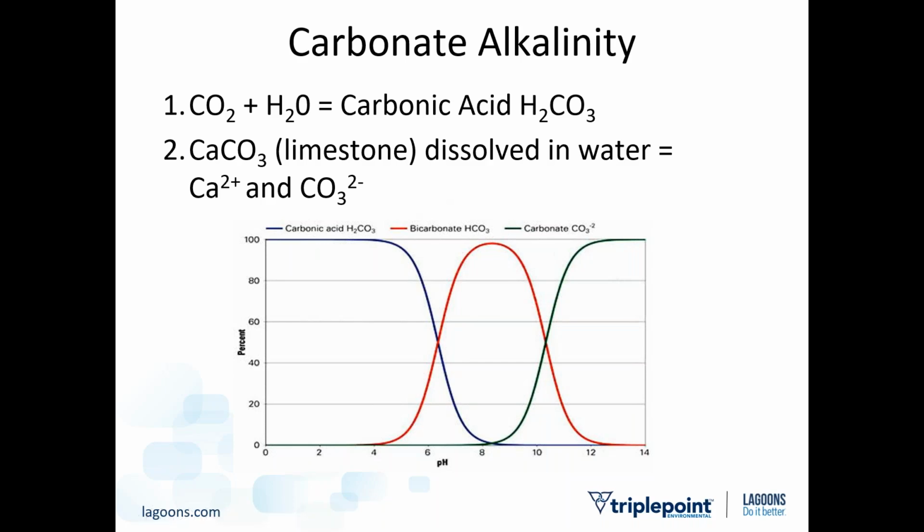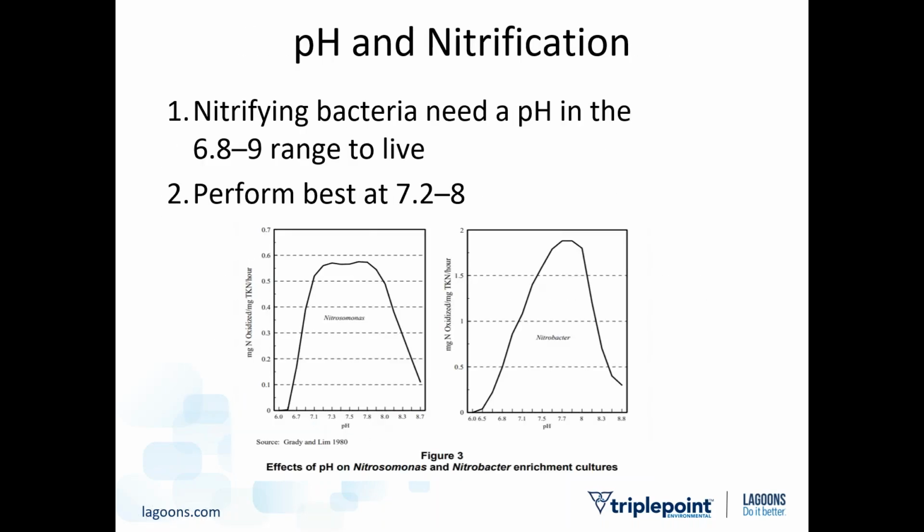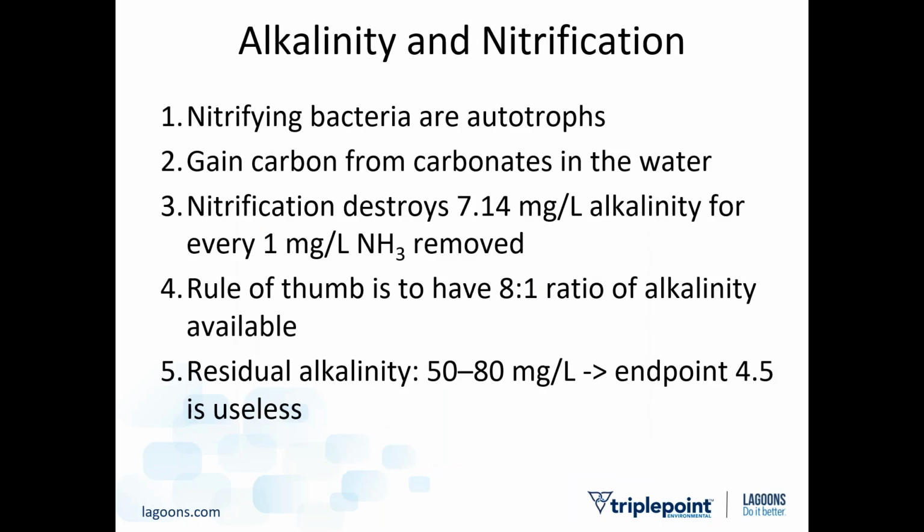And why do we care? Why am I telling you this? The reason we care is that carbonate alkalinity is an essential building block into the nitrification process. So if you've got bacteria that are trying to remove ammonia, they actually need that carbonate alkalinity to live.